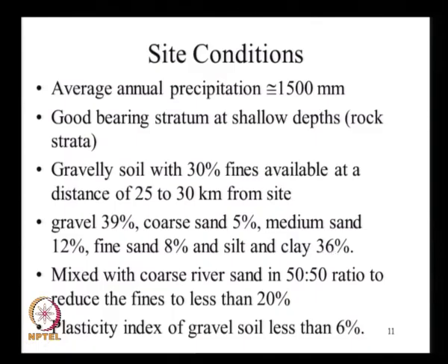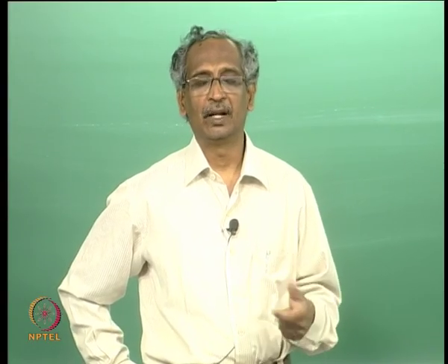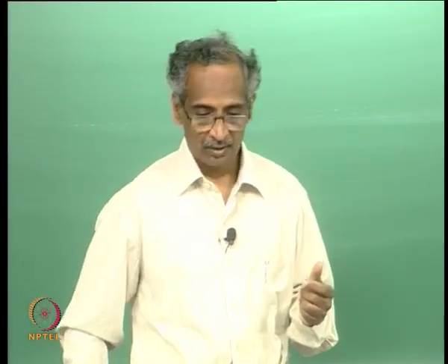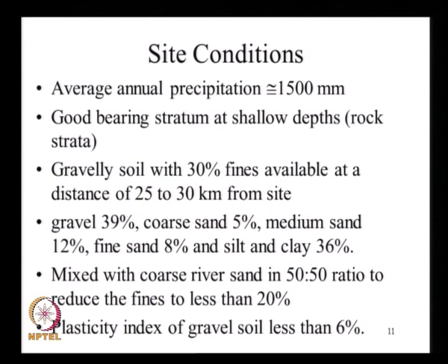And as we have already discussed, any soil with fines percentage more than 15% is not allowed as per the relevant codes of practice. So, it was proposed that we bring in this soil, but mix it with the river sand that is available to some extent nearby in 50-50 ratio to reduce the fines to less than 20%, and it was mixed locally at the site,